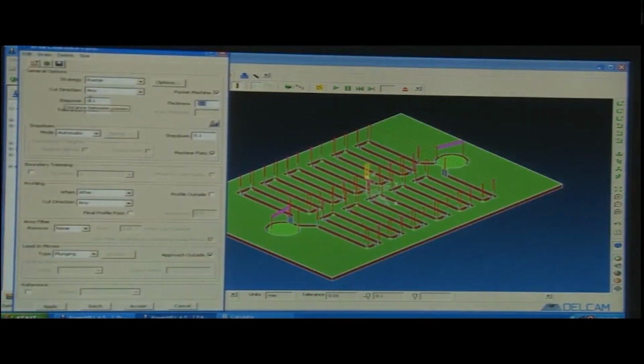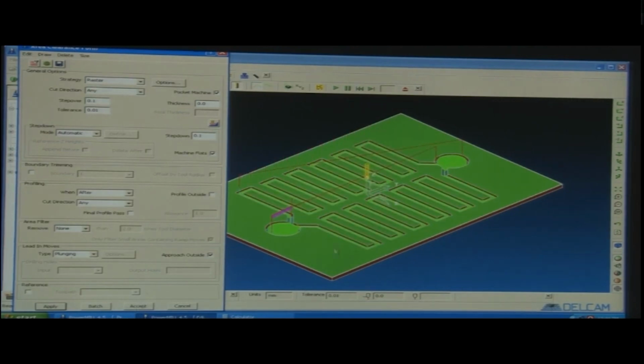So, we can also stage this strategy. What I did was put the thickness as 0.1 mm. Now, let me try to change the thickness to 0 and we can see what this is showing. It is just 3 mm, 5 mm, this is just a tool profile, tool movement in a rapid mode.